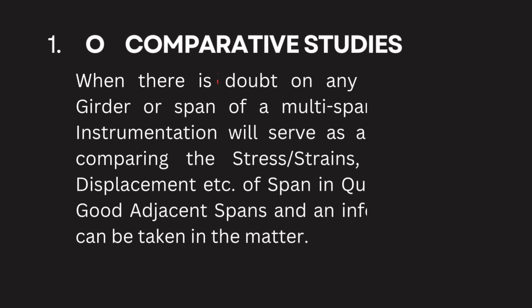When there is doubt on any one particular girder or span of a multi-span bridge, then instrumentation will serve as a good tool for comparing the stress strains, accelerations, displacement, etc. of span in question vis-a-vis good adjacent spans, and an informed decision can be taken in the matter.